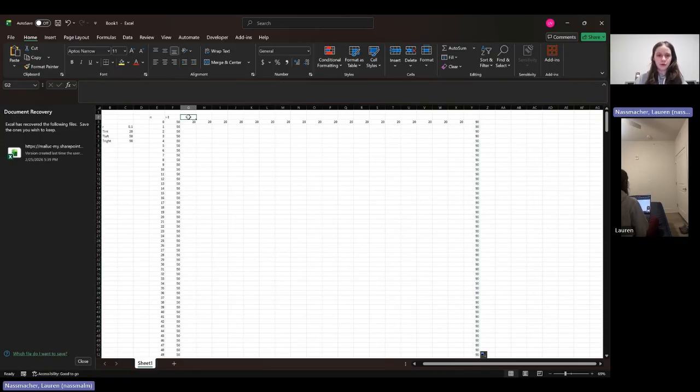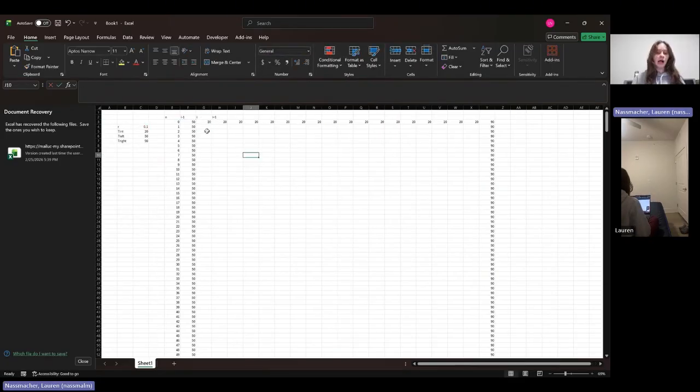This will be our node I, and this will be our node I +1. So we just derived the explicit finite difference equation from our one-dimensional heat diffusion equation. And we're going to plug that into the spreadsheet in order to determine at what point our key parameter, our R value, makes the temperature unstable.